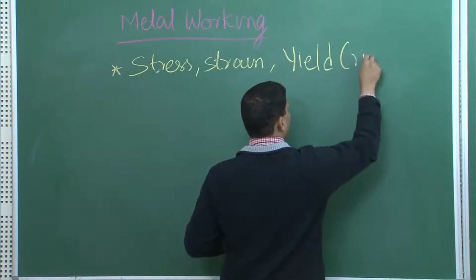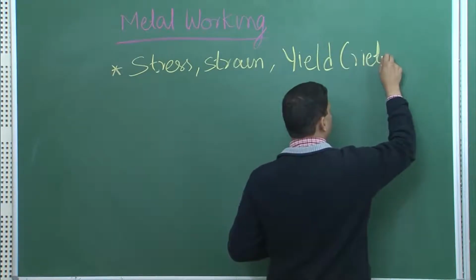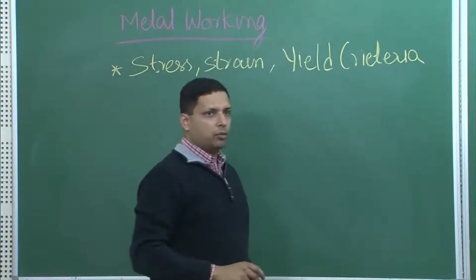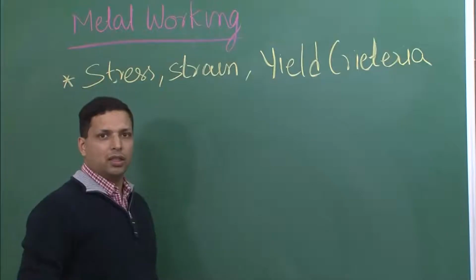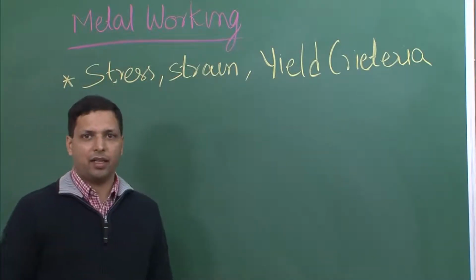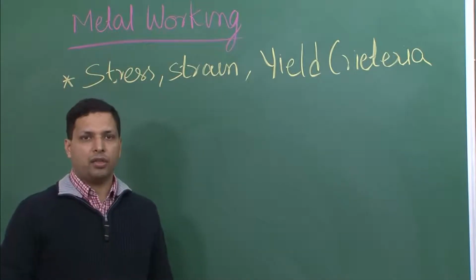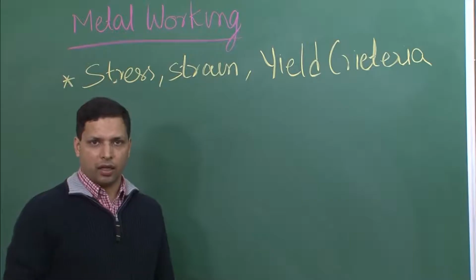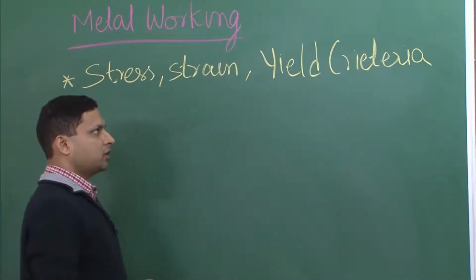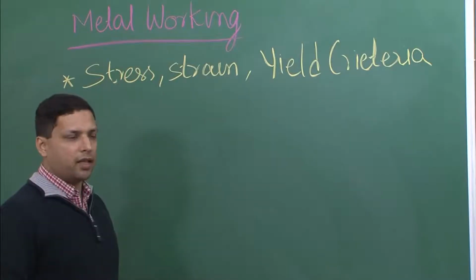because whenever you are doing any kind of deformation, which is a large fraction of the processes that come under metalworking, you need to understand the yield criteria, because we cannot simply define those in our original simple terms of the tensile test and the yield plasticity from simple uniaxial tensile tests.